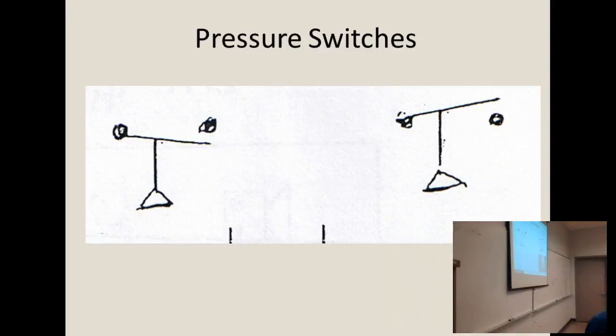Pressure switches. So, got a different kind of flag, right? The one we looked at the other day was temperature, right? So this flag means pressure. And we can have a low pressure switch, a high pressure switch, right? What kind of pressure switch is this one? Open on high pressure. That's right. When the pressure builds, boom, opens up, protects my compressor, hopefully.